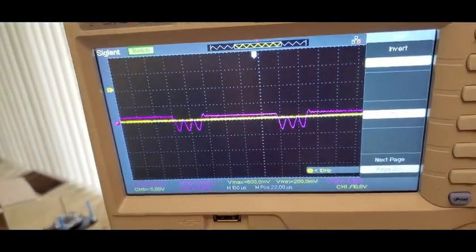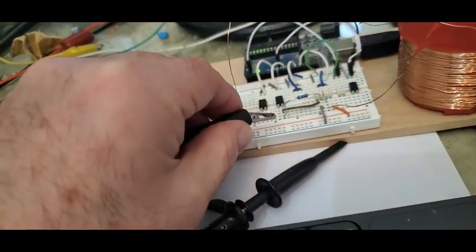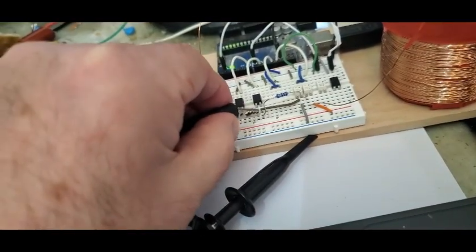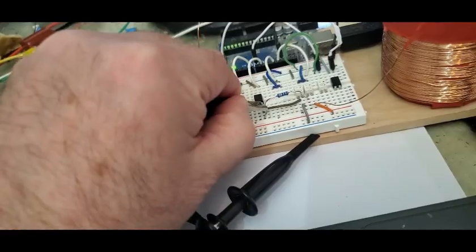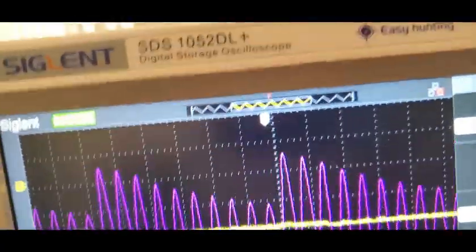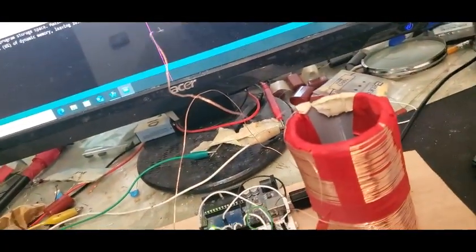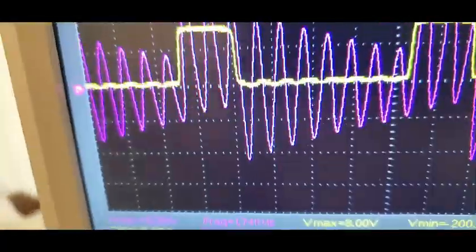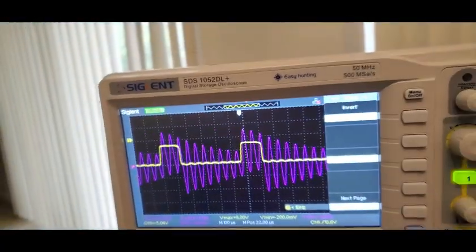And at first it doesn't look like much, huh? But we've forgotten something, haven't we? We always had another ground hooked up there, so I'm just going to put this ground so that we have ground there and there. Now that's what we see. And we can even look at the oscillation. There's our square wave. There's no oscillation, a tiny bit. I don't know, that's just the resistor that it's across. So it's hard to get rid of these oscillations.